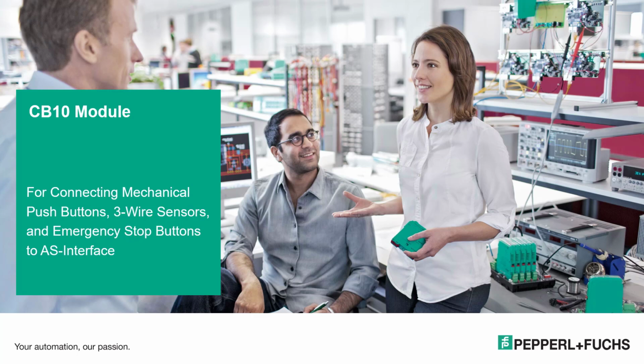The CB10 module is used for connecting mechanical push buttons and selector switches, 3-wire sensors, and e-stops to ASInterface. Safety models do exist, and I'll discuss those later on.